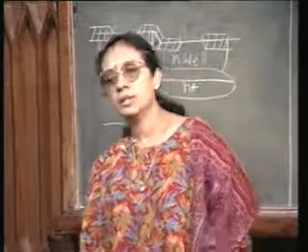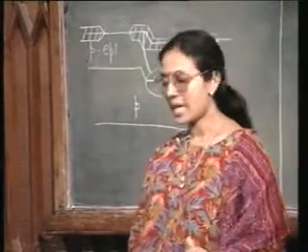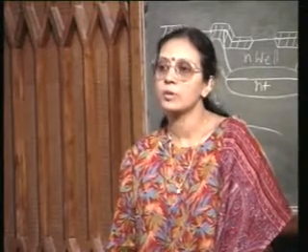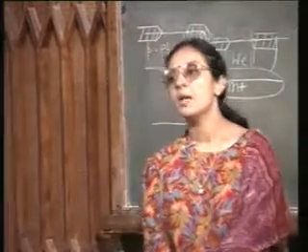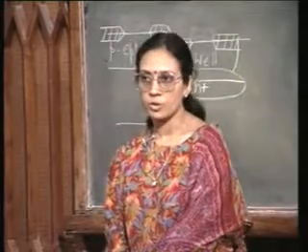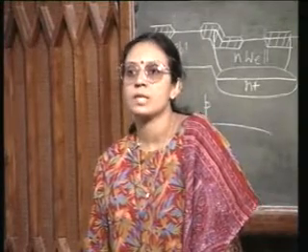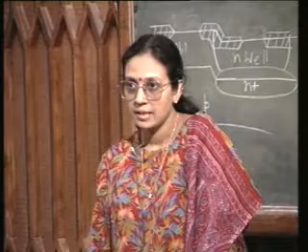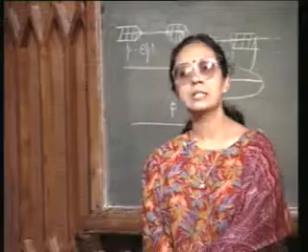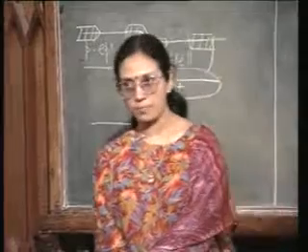Well, this is looking at it from a very optimistic angle. As a matter of fact, it is not just one step, you need to do other things to improve the performance of the bipolar junction transistor, but the basic point remains unchanged. That is, it is possible, as the CMOS technology is getting more and more complex, so that we are going to use epitaxial layers and buried layers. It is going to be possible to incorporate a bipolar junction transistor in the CMOS process flow by only putting in a few extra steps.